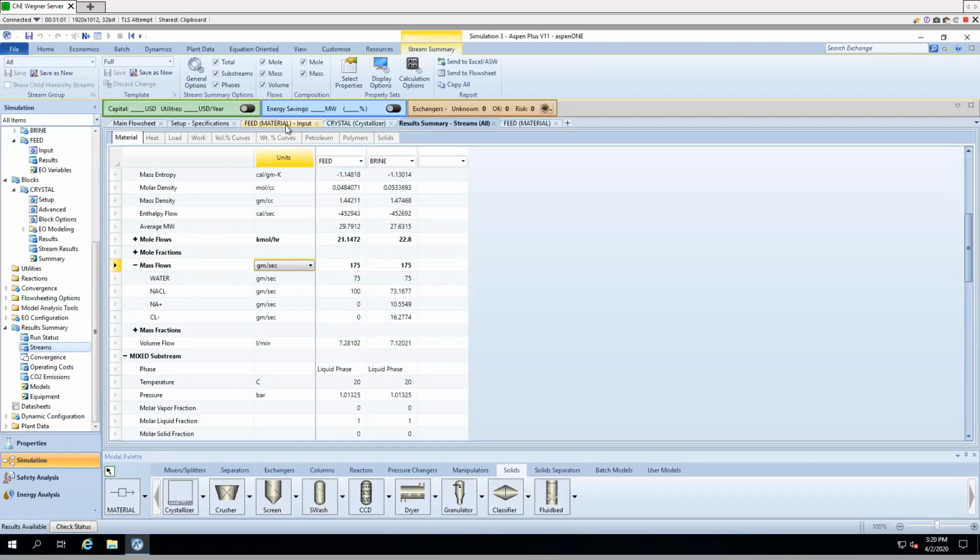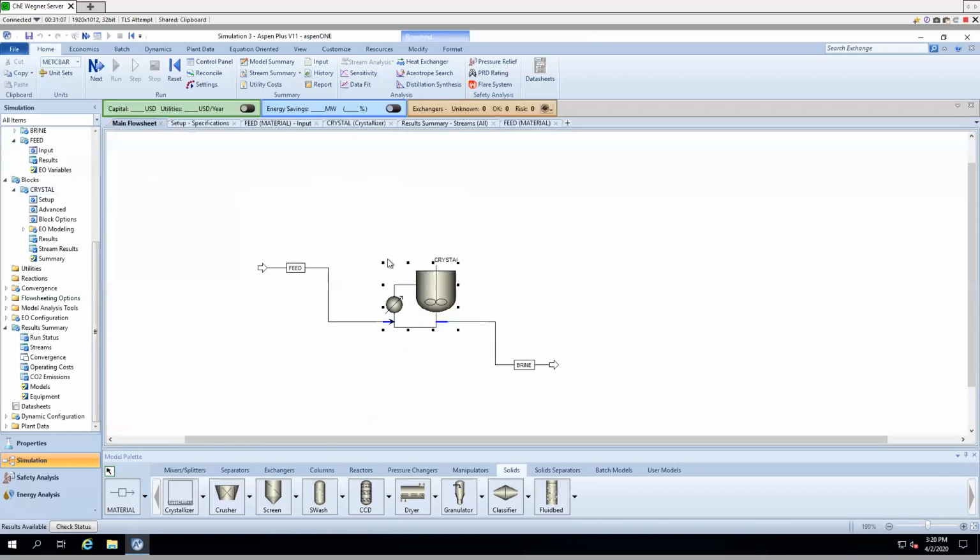And so for part of the homework, they ask, what operation would you change for this crystallizer, this here, to produce more solid sodium chloride? And really, the only thing you can do is give it less water. Because, and I checked this using some analysis tools, there is no pressure or temperature where you get more than like the 10% he wanted.